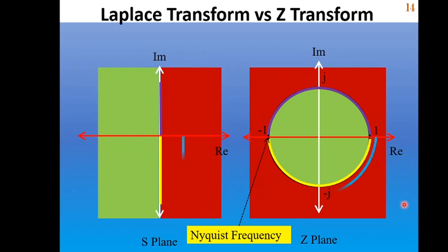The points shown in blue color correspond to the line where the impulse response increases over time. And along this gray line, impulse response of a system decays over time. These points along this green line correspond to the points of constant frequency. If the point crosses the unit circle, then the impulse response of the system becomes unstable.